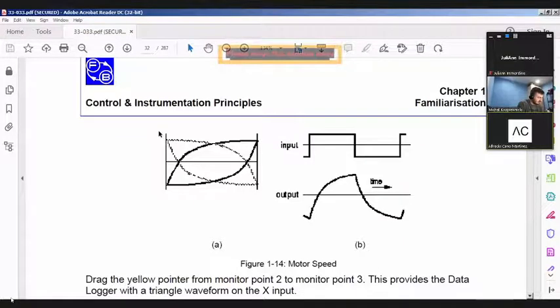One of them will make the transient better, and the other one will make the steady state better, right? So if you max them both out, one of them will try to fix what the other one is actually making worse, right? So these are conflicting actions when you max them out. That is why in PID you usually have something called tuning, where you use the ideal gains for the application that you want to have.